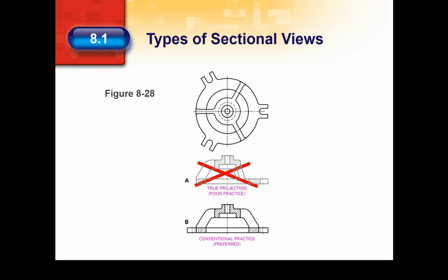When drawing such a view, follow the example of Figure 828B. In this drawing, the ribs and lugs have been rotated on a vertical axis until they appear as mirror images of each other on either side of the center line. Their true shape is not shown. Note that only the parts that extend completely around the vertical axis are shown with section lining.